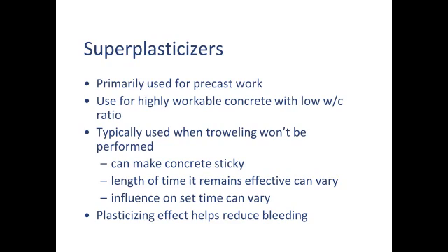And because we don't have to use so much water to get the workability, we don't get lots of bleed water because there isn't a lot of excess water to make bleed water. So you will find superplasticizers advertised as helping to reduce bleed water. Well, that's why, because you don't need as much water in there in the first place, and if you don't have it in there, you're not going to get it later on.